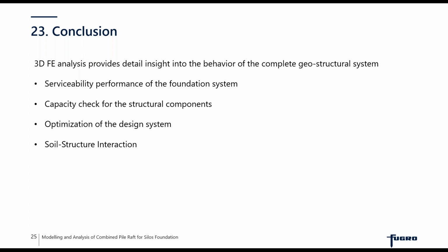In this particular project, the analysis was more to check the serviceability criteria, the settlement criteria of the system working under various load combinations, and by considering the various interactions between the structural components, which in this case were raft, pile, and the feeder tunnels. Also, regarding soil structure interaction in recent analysis, you can find various webinars done by the team of MIDAS, where you can completely bring the superstructure in as well and model the soil.